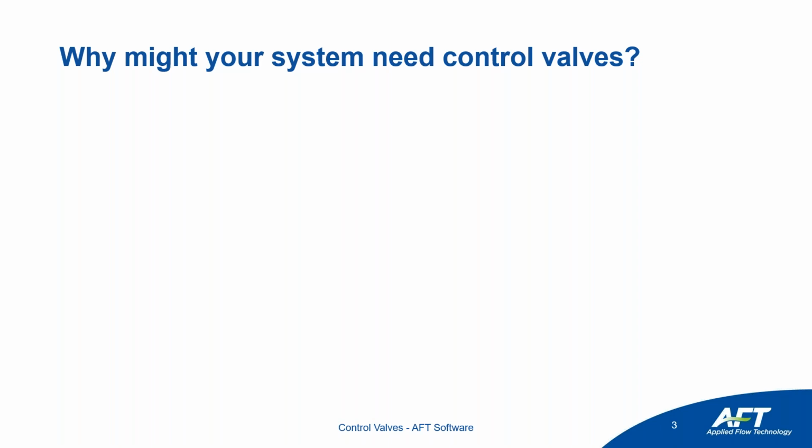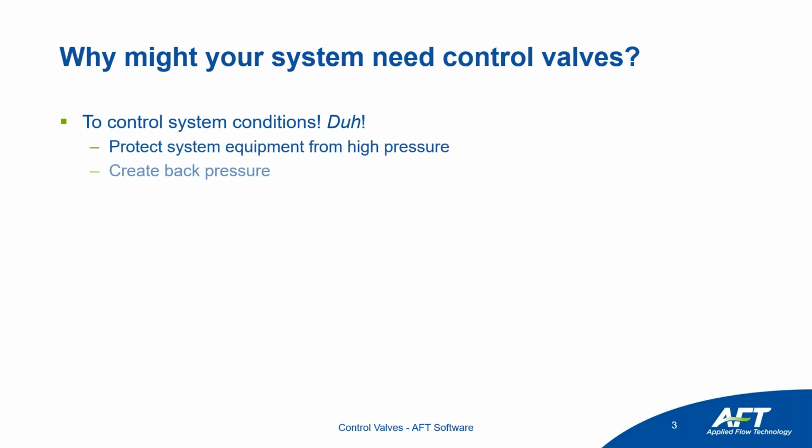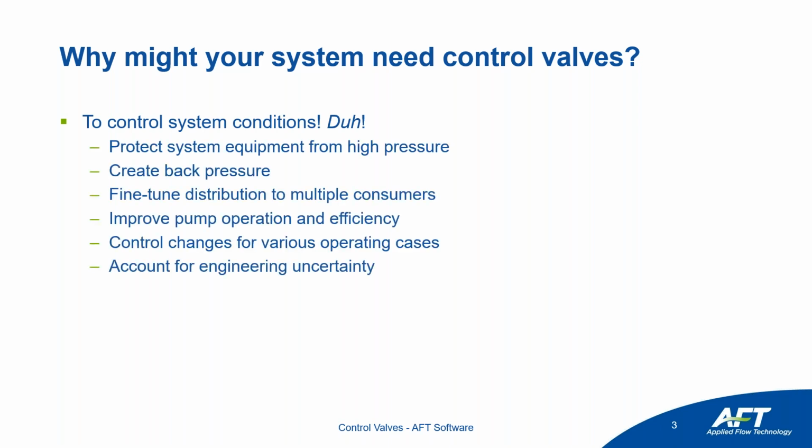So the first question we should answer is, why might your system need control valves to control your system conditions? That can mean a lot of different things to a lot of different people and systems, whether that means protecting equipment from high pressure. Maybe you need a valve to knock down the pressure, or you need to sustain pressure and create back pressure for your system. Another common application that we see, especially in cooling water or distribution systems, is maintaining distribution to multiple consumers. It's challenging to rely on fixed elements directly or the hydraulics of the system, so having an element that can vary its losses to fine tune that mass flow rate or pressure supply.